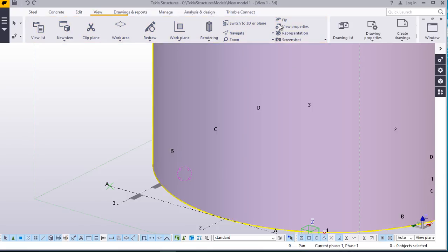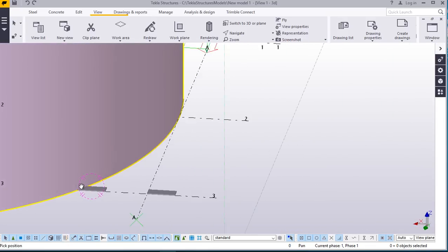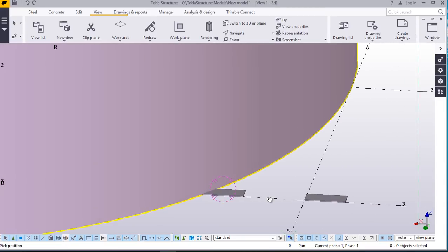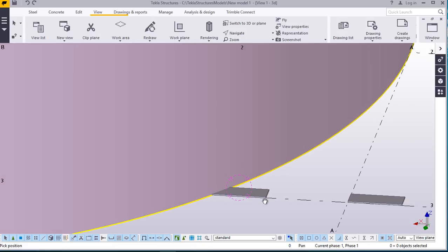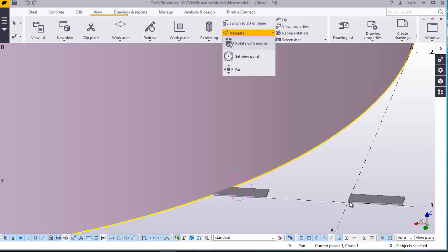Just how you can create a plate using a contour. I've demonstrated that on several videos on this channel. Now we want to create a staircase for our tank, and prior to doing that we have to create a thread elsewhere, then you bring it closer like this. To do that, you snap at the bottom here.